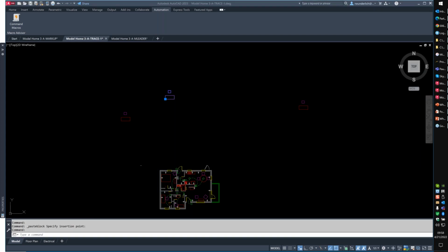To add full paths to do this depends on how your sheet set was initially set up and whether or not all of your sheets, if the drawings themselves are stored in BIM 360 and the DST is stored in BIM 360. If they're not in the same folder, that might be part of it. If they are in the same folder, then I would definitely reach out to Autodesk and let them know. There is a theoretical limit to how many sheets you can have in a sheet set. Just know that 40 should be fine. If I remember it, the limit's 255. Once you hit 256, it breaks.